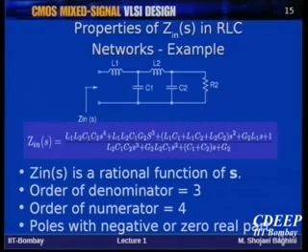There are components in the circuit which are able to convert energy from one form to another and then increase the amplitude of the original noise which exists in the circuit. But if you have all components which are lossy or lossless, but they are not generating any new kind of energy from the original noise, they cannot increase the amplitude because they are passive, not active, not able to increase power. Therefore, you cannot get any unstable situation in the circuit. That's why all poles are limited to the closed left half-plane.